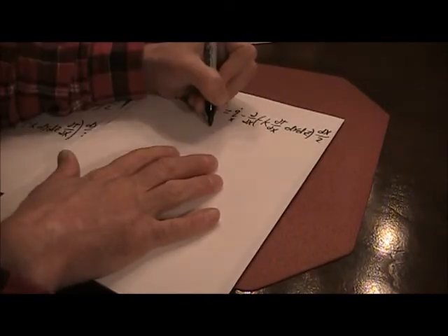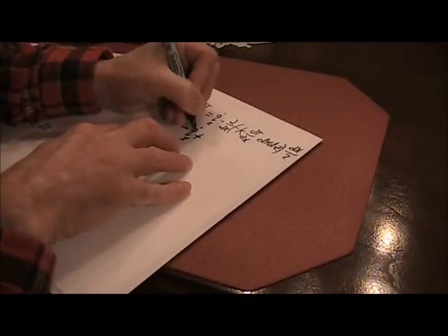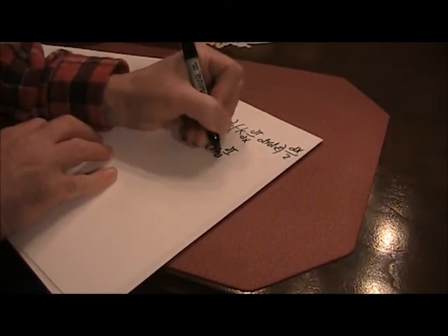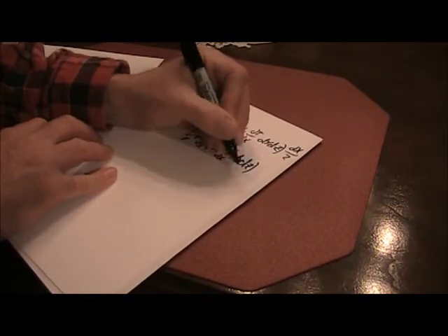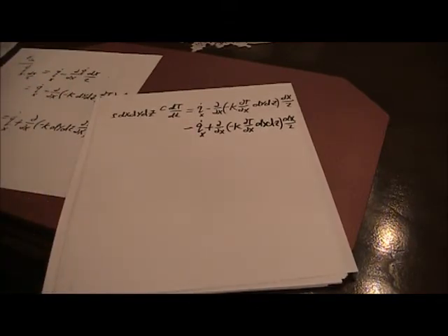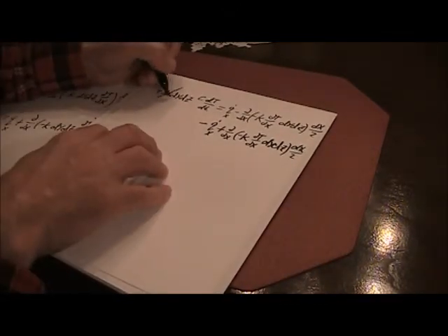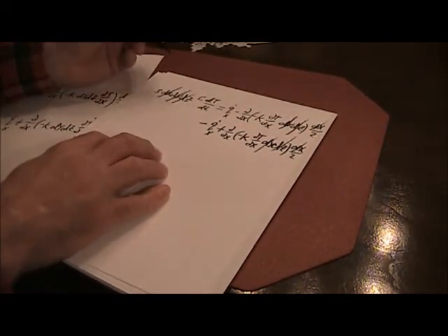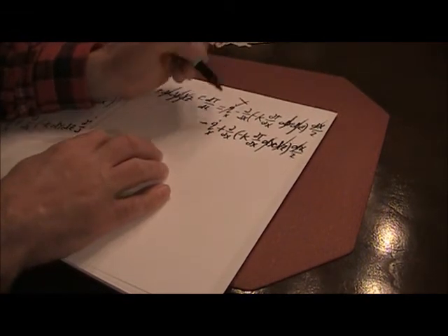Then minus the energy going out, which we just saw is equal to Q dot at x plus the change with respect to x times minus K dT/dx delta y delta z times delta x over 2. And we can simplify this down further. If you do some more algebra here, we can divide the volume out, delta x, delta y, and delta z. And Q dot x goes out with this one.